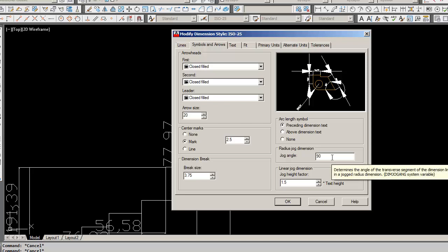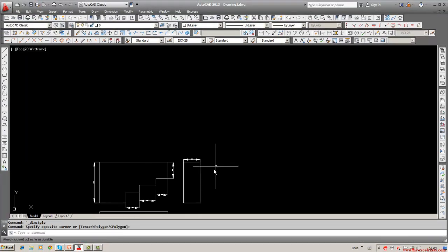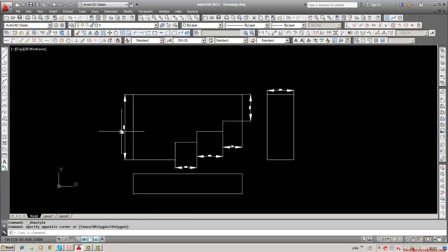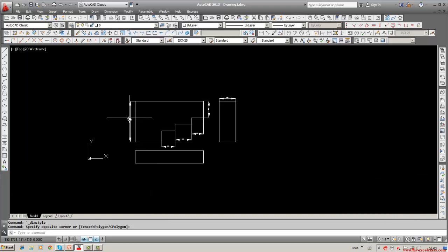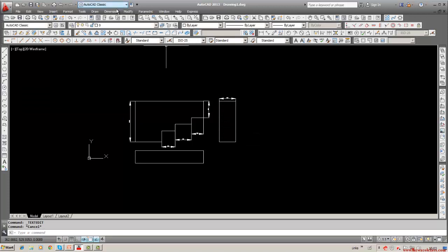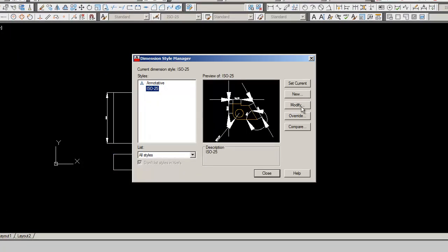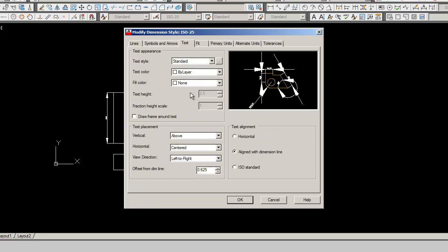Then all these things are now jumbled up, so I have to make the drawing bigger size to explain it very clearly. I will just close this and see how it looks. See, arrow dimension is 2.5 only, so I will slightly increase the dimension style. I think I increased it, but it has not. See, modified text. Oh, it has not taken up the modified.